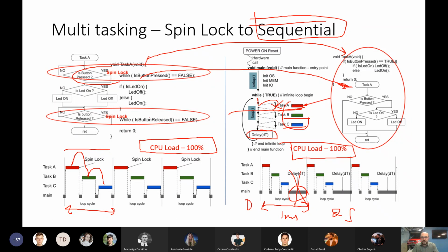because we will go inside the delay function. We will see there something like a down counter that is counting down the value that you provide to the input. And when the down counter reaches 0, we will get out. But we are doing something. We are counting down and doing nothing. So delay is not about not doing anything. It's about doing nothing, so we do something that means nothing.